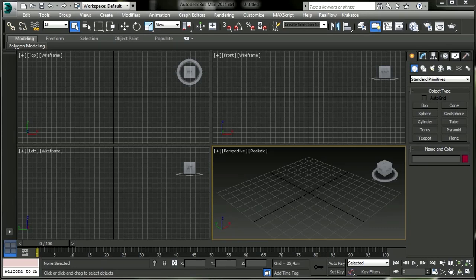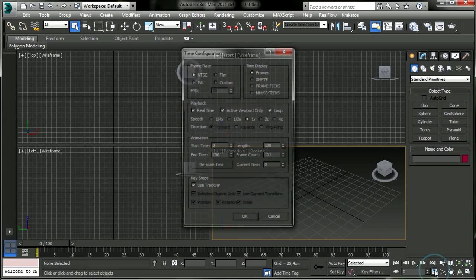Today we are going to see how to create a large scale smoke effect within 3ds Max with the plugin FumeFX. There are a number of ways you can create these plume smoke effects: with a simple source, an object source, and a particle source. In this tutorial, we're going to use Particle Flow to emit particles, and then a particle source to help FumeFX emit the fluid from these particles that we've created.